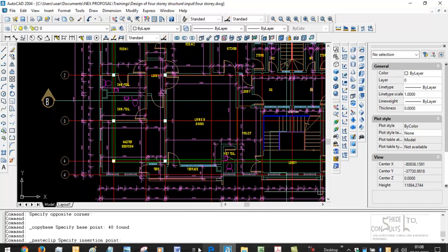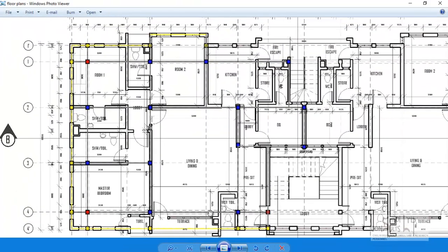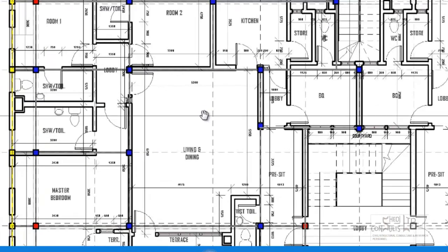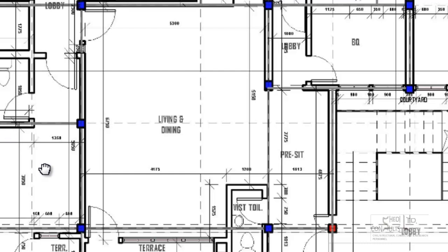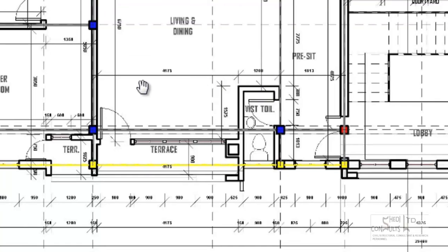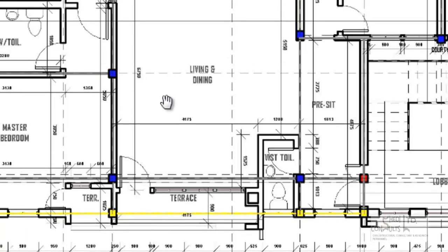So based on this, what we decided to do was to flag up some of these columns so you could see the position in which the architect has originally presumed the columns would be. However, when you develop your preliminary structural framing arrangement to carry the superstructure, you may find out that the column positions may either be uneconomical or may interfere with the original aesthetic of the structure. In our own instance, we saw, look,